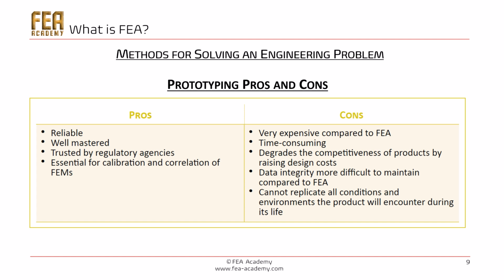For the disadvantages, they are very expensive compared to finite element analysis, and they are time consuming. It takes a lot of time to build a specimen, to build a jig for doing the test. Also, it degrades the competitiveness of the products by raising design cost. The data integrity also are more difficult to maintain compared to FEA. And finally, they cannot replicate all conditions. Okay, we have a lot of limitations with prototyping.